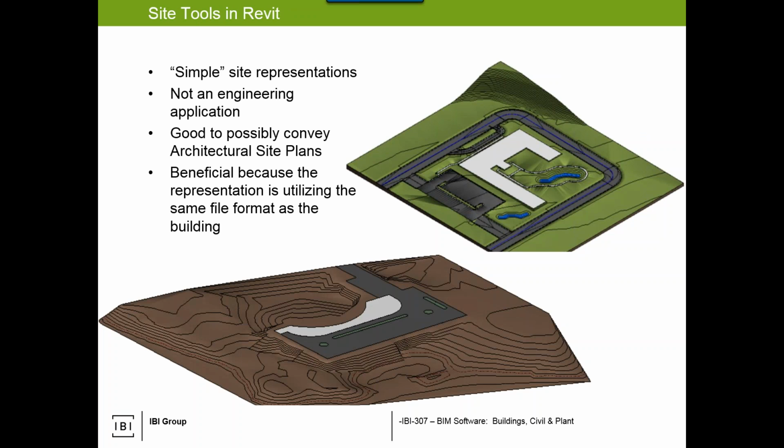Revit has site tools, and I bring this up here because there's a lot of confusion when people open up Revit and say, well, we'll get our civil modelers to use Revit because you can do this. Right? And I describe these as simple site representations, but not to be confused with the engineering applications that Civil 3D and InRoads, GEOPAK, MX have as integral to them.